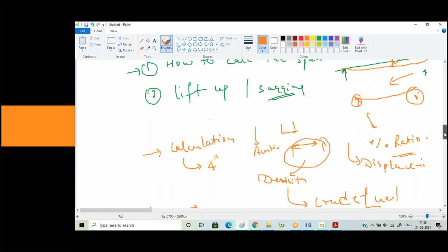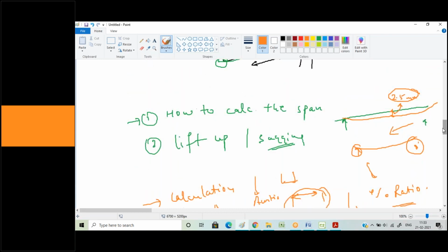Now the other thing he was saying: if there is a case of lift up, say my pipe is actually not resting on the supports, he would use the word that my pipe is not resting on the support. These are different scenarios, but we are clubbing them all together and letting you know. Lift up has a lot of conditions again. One, when your pipe is operating and then lifting up from the support, it's a different condition. In operating case, a lift up is a different condition.